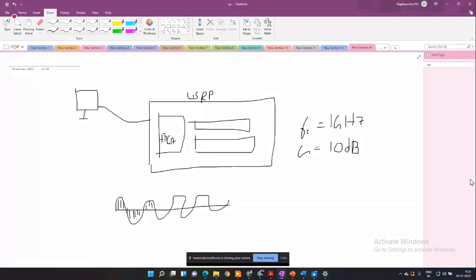There is basically an EEPROM sitting inside, an electrically erasable programmable ROM. When they calibrate it, you will get the unit of dBm. But when NI gives it to you, it will be only in dB format. Unless you calibrate it yourself or have someone calibrate it for you, everything is in relative units.